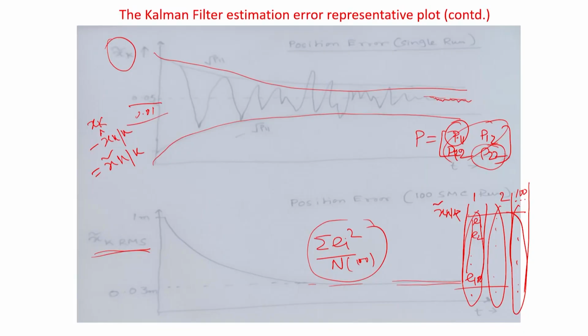The Cramer-Rao lower bound is the theoretical minimum mean square error bound, or RMS error bound, which your estimator's error should physically respect. Now, if the estimation error you have plotted here is going near to your Cramer-Rao lower bound, that means your filter is converging and doing its job. Okay. So, you may ask me one question: I understand my filter is converging.